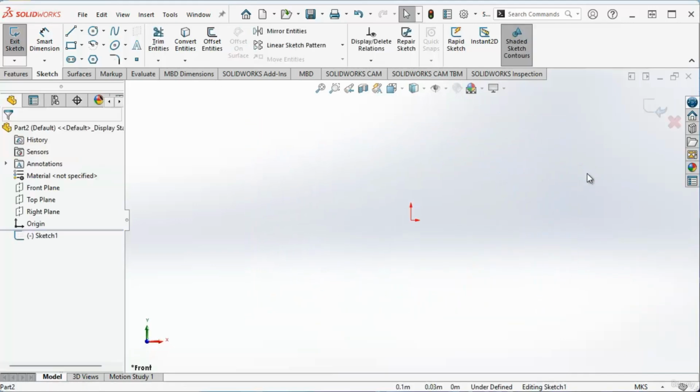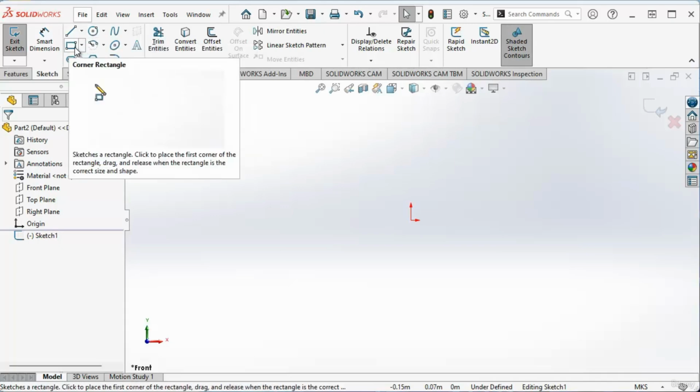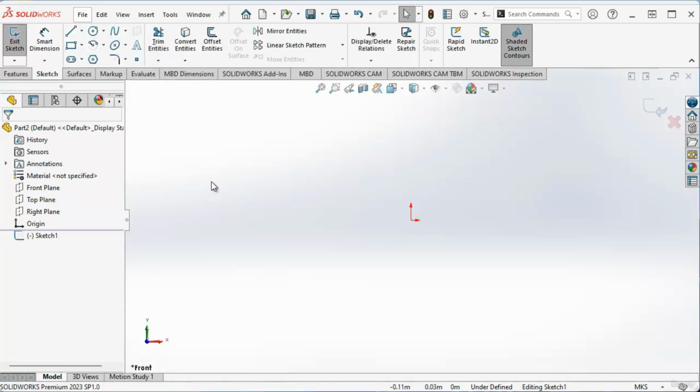So I'll select this front plane maybe, and you can see we have entered inside the Sketcher workbench. Here we are presented with this plane. In this, all the tools that you have: this set of tools is for creating some geometries like line, circle, rectangle and so on. These tools are used for editing and modifying those geometries. We will see them a bit later.